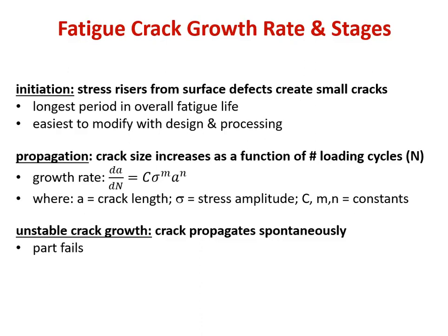And we would do testing and identify those constants, and then for a similar loading scenario, the same offset and the same load amplitude, we could then predict how long it would take to grow the crack in a service situation, again provided that those conditions are the same. And again, of course, as soon as the fatigue crack length A exceeds our K1C criteria, we'll get failure. However that crack started, you'll get failure at that point.